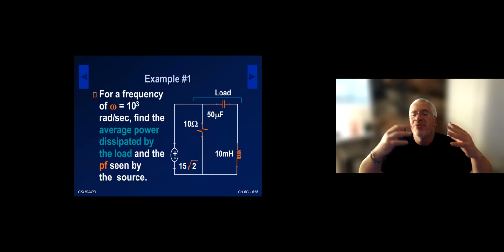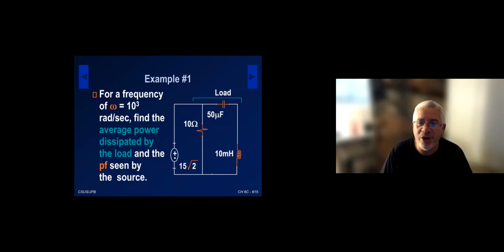Okay, so I'm hoping at this point you can answer with a measure of confidence that the average power that the 10 millihenry inductor dissipates is 0. The same thing for the capacitor, because these are purely reactive elements, and we've actually convinced you that if you have a pure inductor or a pure capacitor, the average power dissipated is 0. But we'll show that in essence here.